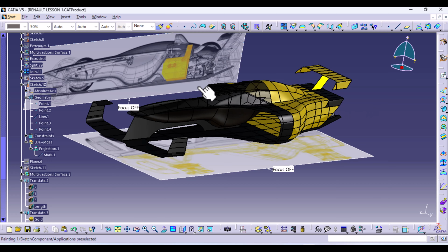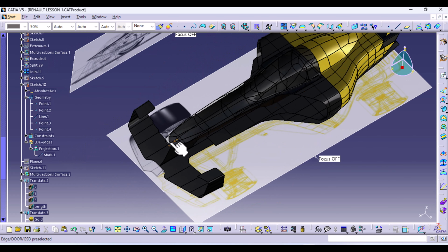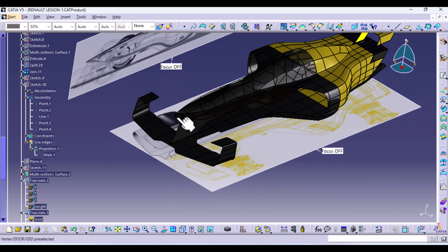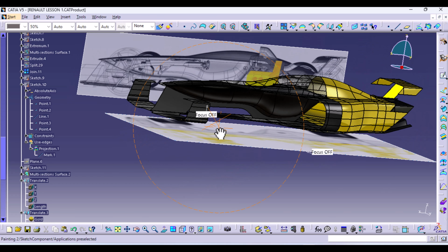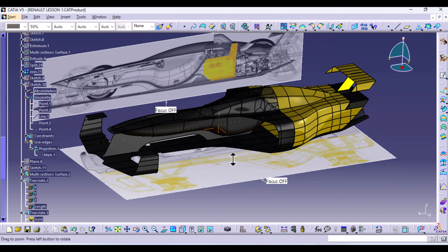And some more details I can mention is there's a ribbon running around this edge. So with that, you can just create a boundary along the entire edge, and then create a small profile of, let's say, a circle or an ellipse, and then sweep it across the entire profile. But basically, this is how you create the mainframe of this car.